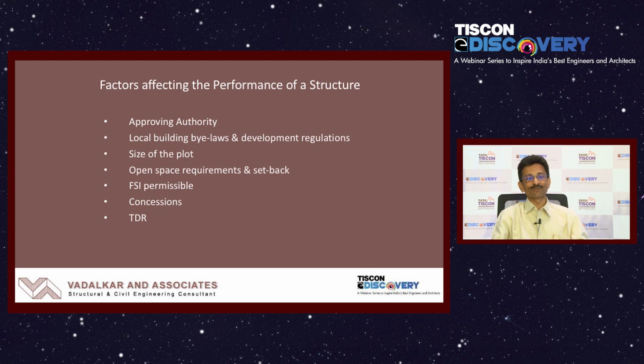Then of course the size of the plot also matters, because based on the size of the plot you have to keep the open space requirements and the setbacks. The architect has to plan based on that. If the plot itself is of odd shape or very narrow, then we have limitations in planning the building itself. So that is another factor which finally affects our performance. Then the FSI permissible in the particular area decides whether you go taller or spread the structure on the ground. Then there are some concessions available for getting building permissions and approvals. Sometimes TDR is bought afterwards, and then the builder keeps on adding floors on the existing structure. So that also affects the performance of the structure.